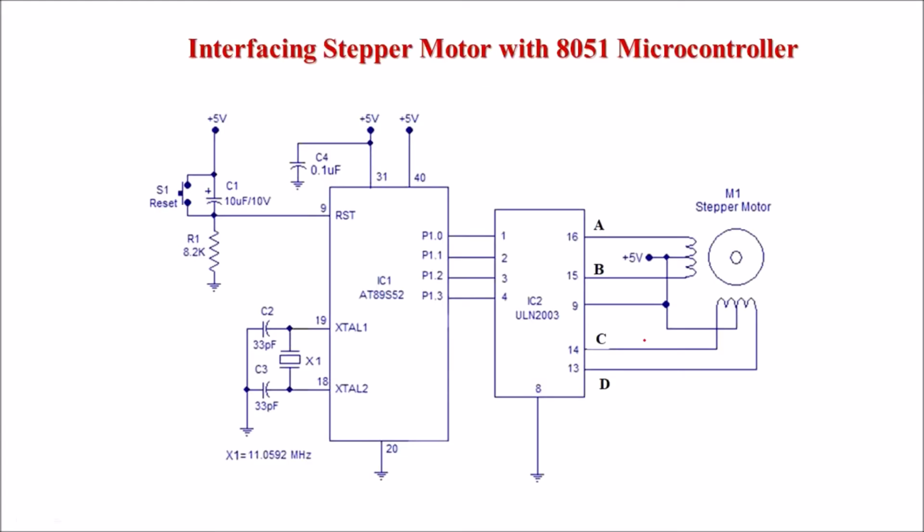Let's go through the interfacing diagram of the stepper motor with the 8051 microcontroller. This is the 89S52 IC and we have connected this stepper motor M1 to this IC through the driver IC ULN2003.